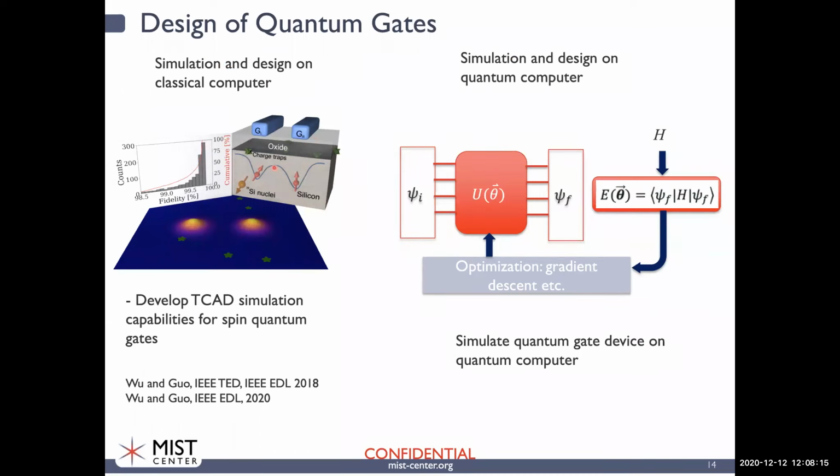We solve quantum mechanical equations and quantum dynamic equations to model the quantum confinement and the evolution, control, and readout of spin information for a spin confined in the quantum dot structure. And we explore important figures of merit, such as the fidelity of the quantum gates, in other words, how accurately these quantum gates can operate in the presence of various quantum noise.